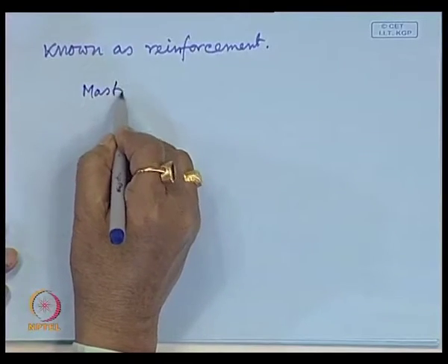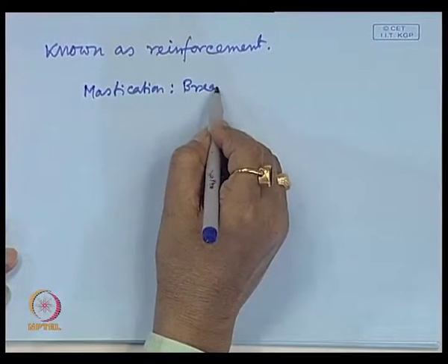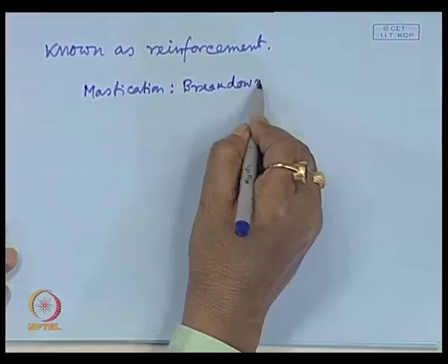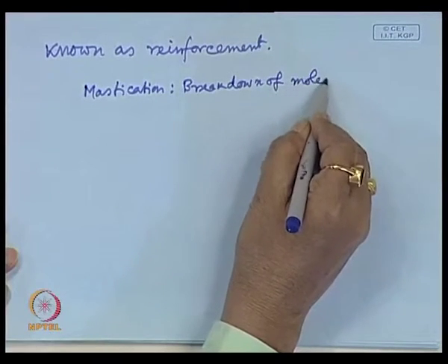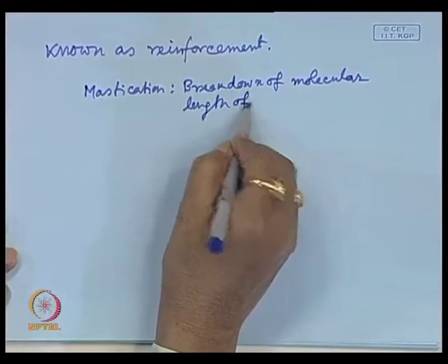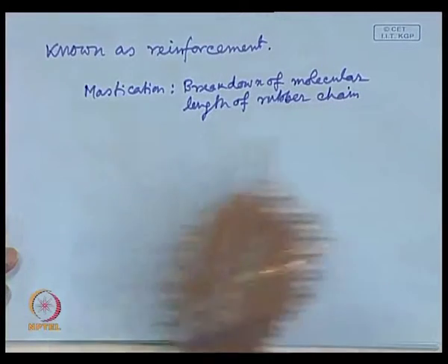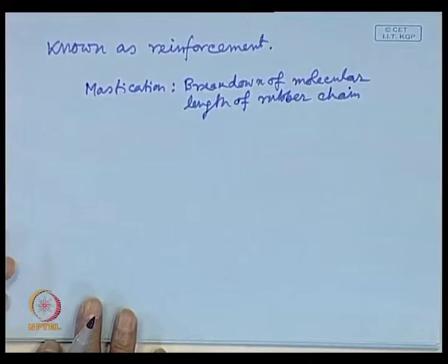By mechanical shear force, it will decrease the molecular weight by breakdown of the molecules, that is known as mastication. Mastication process: breakdown of molecular length of rubber chain.